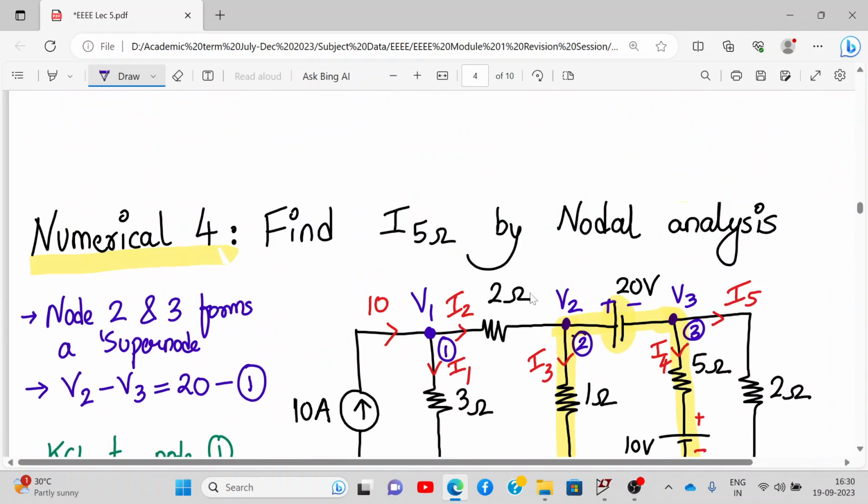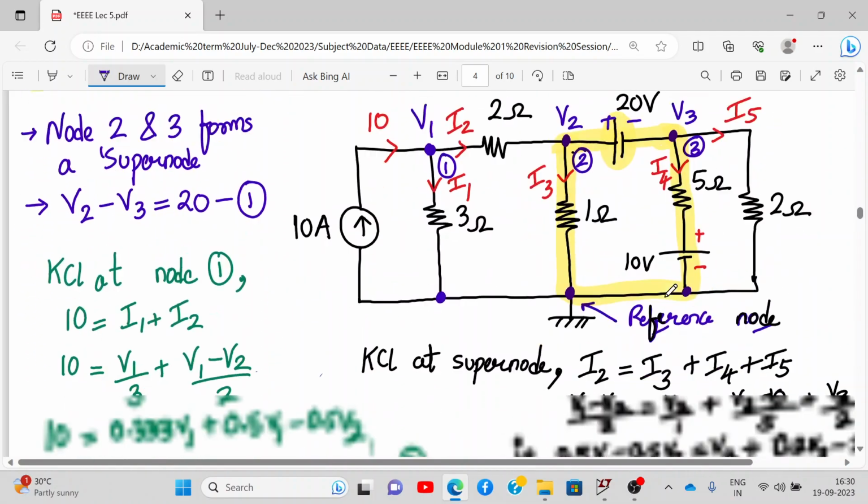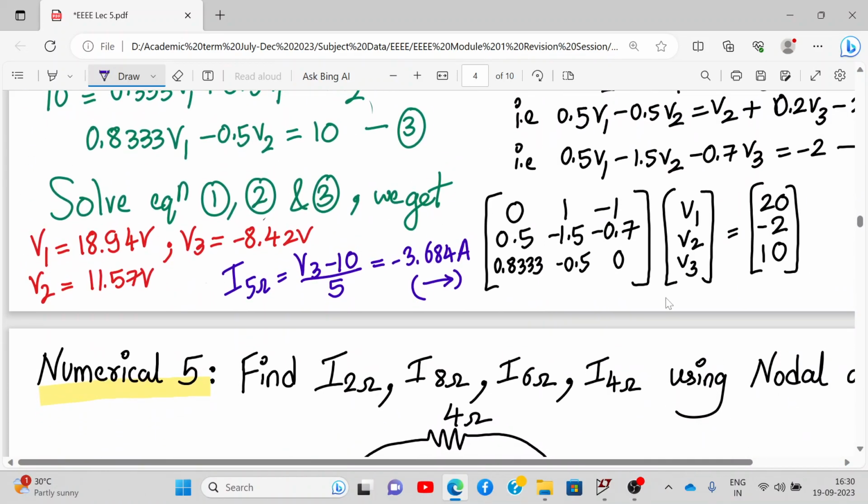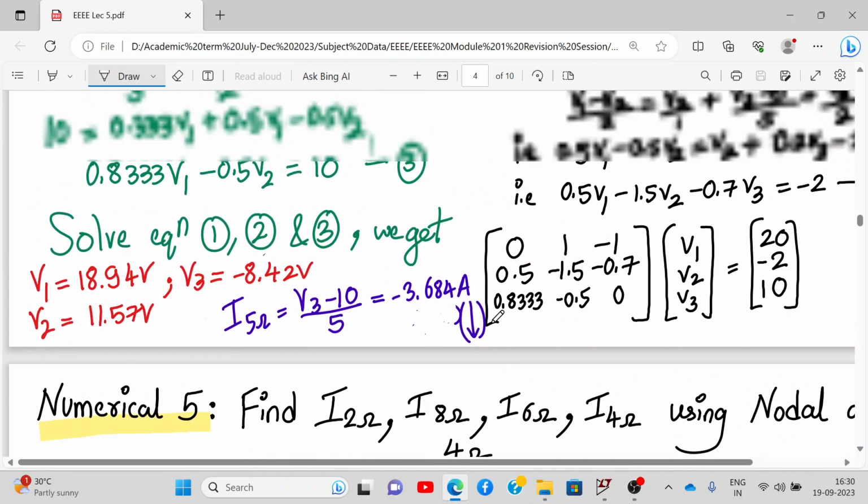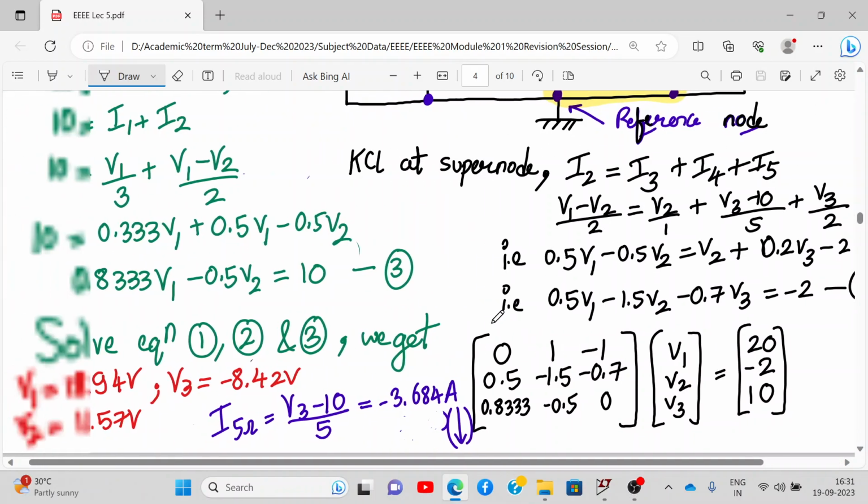Okay, from top to bottom actually. Current direction is from top to bottom and not this. All right. Let us not use an eraser. So it's from top to bottom. So that is the answer which we get, and this is very important in terms of learning the supernode concept. I hope you're getting the answers.